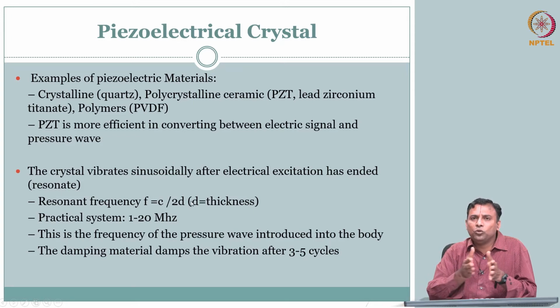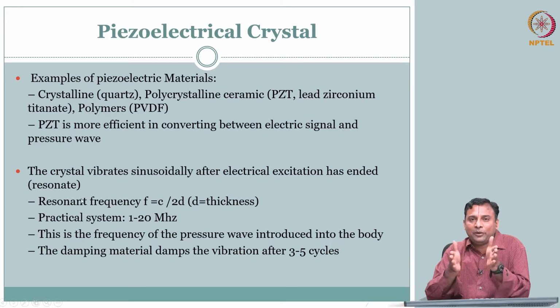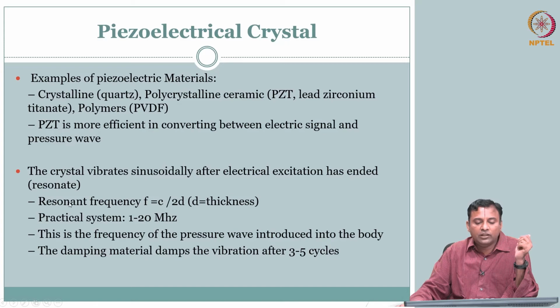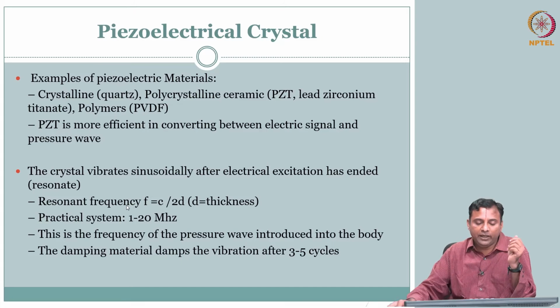Of course, this has to do with the mode of propagation, the crystal, the stress-strain of this crystal, all that we are not really going in depth. Okay. So we have engineered this crystal predominantly to vibrate in only one mode, which is your thickness mode, and therefore your resonant frequency can be specified by changing the thickness of the crystal.